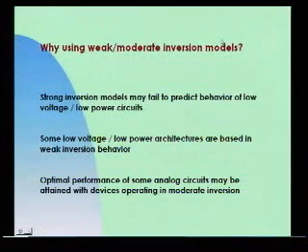And as a third thing I'd like to mention, many circuits like amplifiers have their optimum performance regarding power consumption and size and gain and many other things in moderate inversion, and so you should design the circuits better using a model that is valid also in moderate inversion.